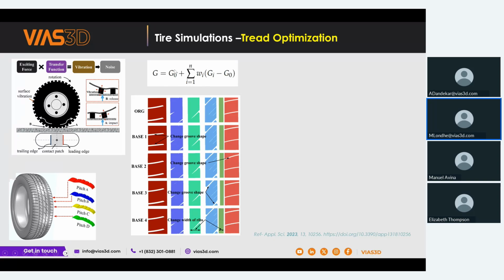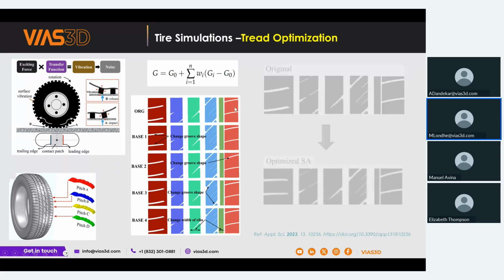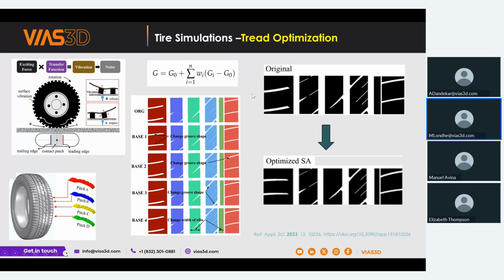And for that, you now use the optimization algorithm to minimize your vibrations, like the excitation force, as well as the output, like your response or nodal displacement. For such optimization, genetic algorithms are very commonly used. When such a simulation is performed, one can see the original tire geometry versus the optimized.